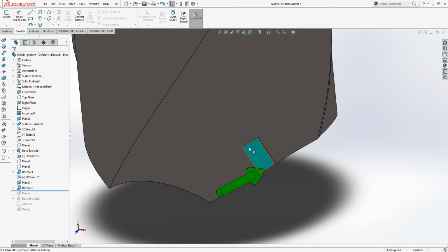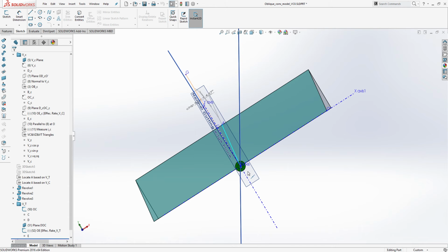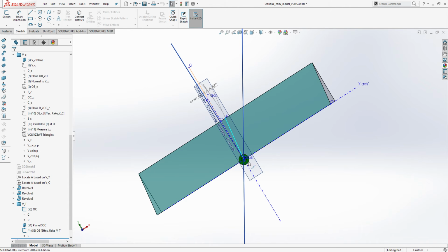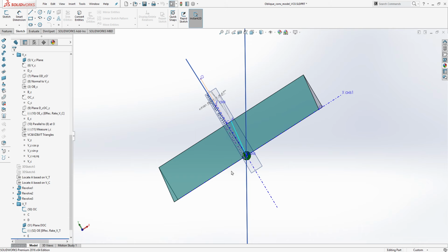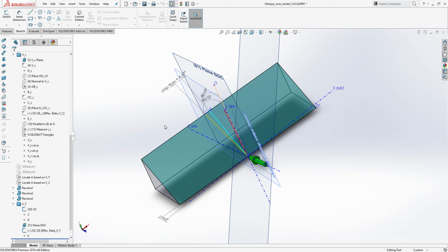If we take one element and observe it in detail, we have this oblique model, which is approximately the same as before, and this has a P angle here, and the green arrow is the tangential velocity. In conventional drilling, it is equal to the cutting velocity. So it looks like this.